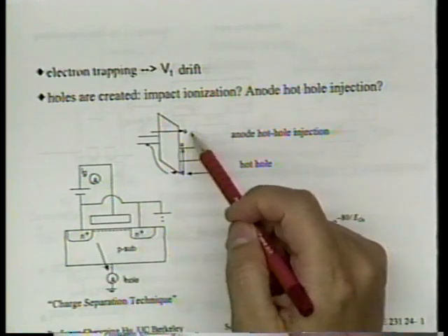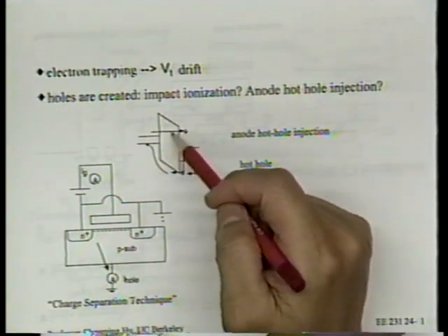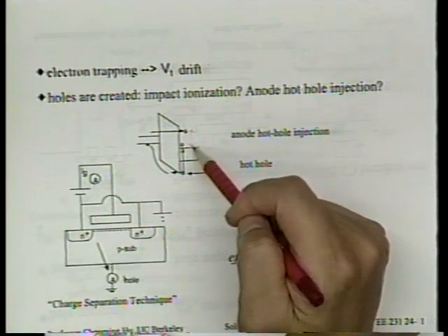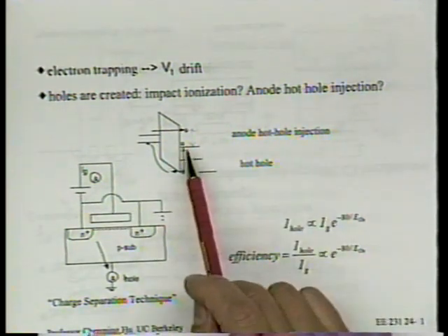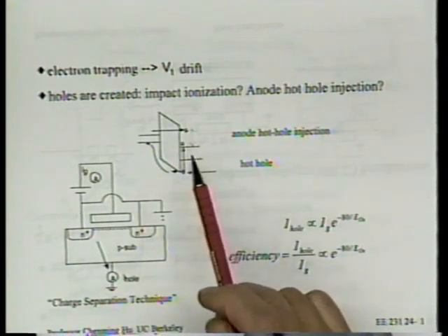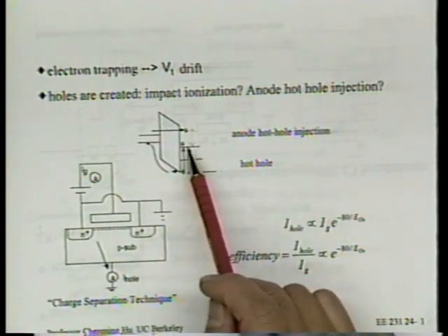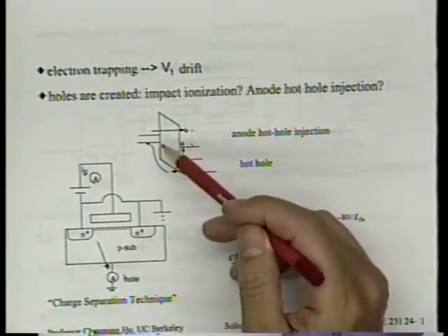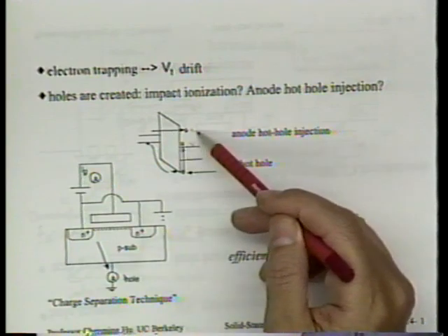Because assuming there's no scattering, when the electron comes here, what determines this available energy? That basically, to the first order, is just the voltage across these two electrodes, right? Just for simplicity, let's assume both the substrate and the gate are N plus silicon. Then this energy difference is really the applied voltage.